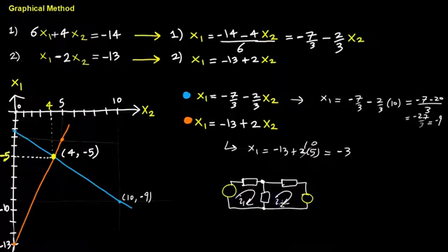So if you were to apply KVL here, the first equation would represent this particular loop, and the voltage rises and voltage drops across each component, and how they relate to the current, and how they equate to zero. Basically, you would say minus the voltage here as you go up, plus the voltage here, and plus the voltage here, depending on the polarities you choose, but the idea is the same. You sum across their rises and falls, that should equal zero.